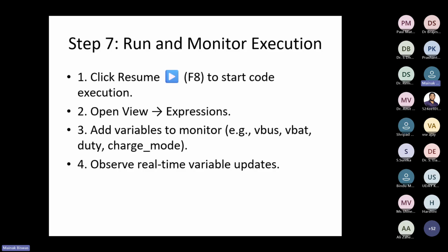Click on Resume to start the code execution, then view the expressions. Those are the variables to monitor, like VWAS, VBAT, duty, charging mode, etc. Whatever we have to define here, those things we have to show in the variable monitors. And it will show the real-time variable updates, like the serial monitors.